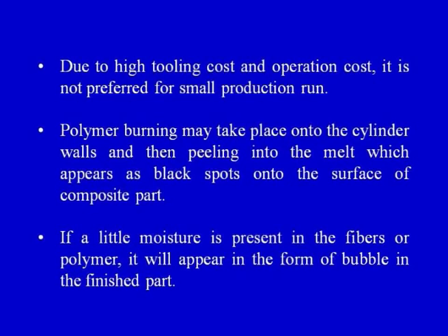So, that is one important disadvantage which has to be taken care of. Due to high tooling cost and operation cost, it is not preferred for small production runs, which is very clear. If we want to make only 5 products, the process is not suitable. It is only suitable for large production runs where we want to produce a large number of identical parts.